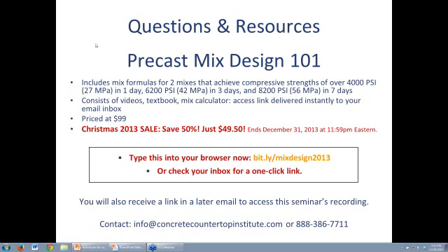What's the best way to get pure white concrete using 100% CSA cement? Excellent question. I would recommend using a very high loading of titanium white. Because CSA cements react so fast and you get stupid strong concrete, you can exceed the 10% limit. So what if you lose a quarter of your strength? You're still making very, very strong concrete. Try a 15% loading and see what that gives you. I've done it and it's worked. I've made pretty white concrete.